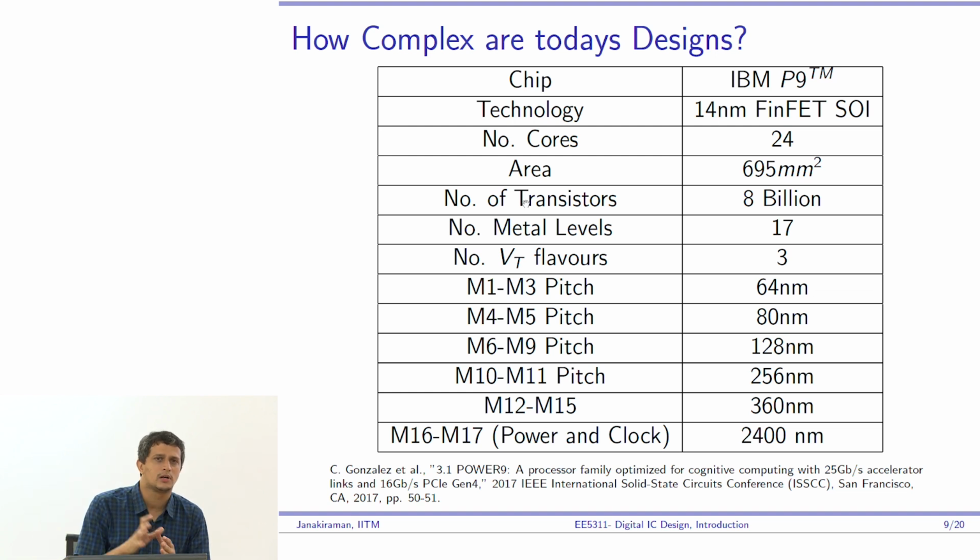So just an order of magnitude question, if the on current is, let's say, 1 unit, what will the off current be like? Order of magnitude. It's about 1,000th, 10 to the power minus 3. That's what a technology can guarantee. Beyond that, it's very difficult, right? So they found it very difficult to achieve this beyond 22 nanometer with the old transistor technology.